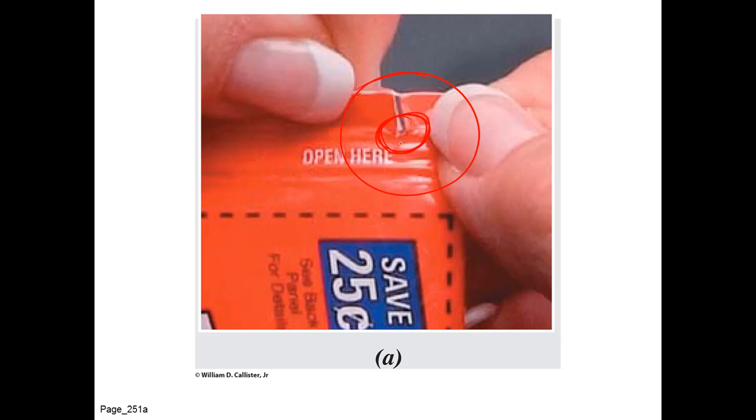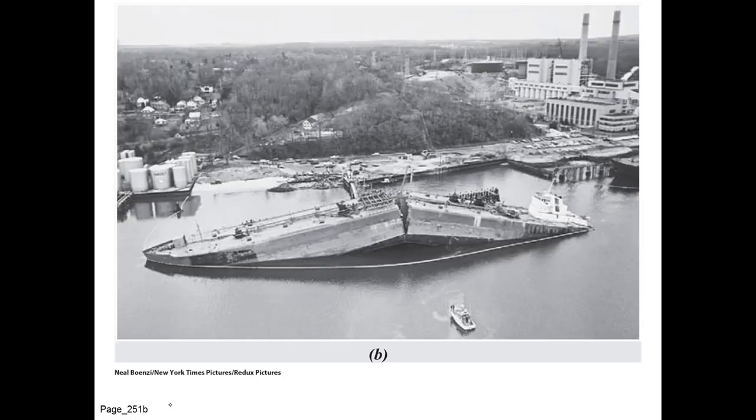This is fairly common in pharmaceutical packaging, obviously, but also food packaging. For example, if you've got an aluminum or steel bottle top that is loaded under compression and then torsion, it will peel off and break the seal, for example, on a pop bottle. So those are design failures, but in most cases, the failure is undesirable.